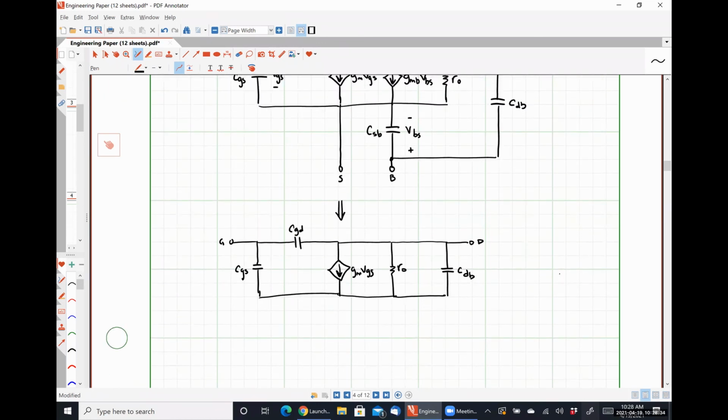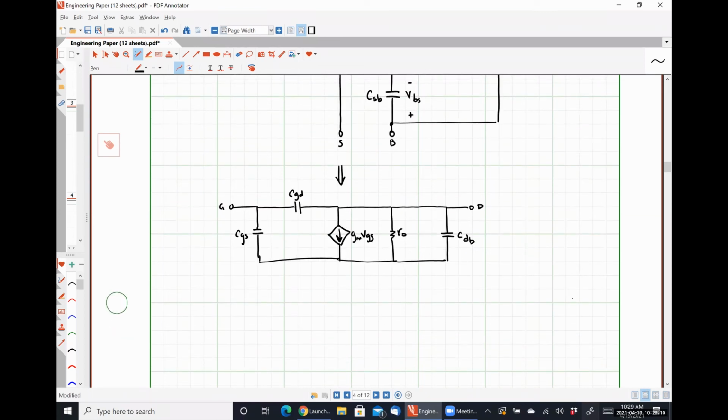And so here's something where legitimately I'm a smidge confused, okay? In the textbook that you guys are using, it explicitly draws a source to body capacitance even when the body effect is ignored. But that capacitance is shorted out, so I don't know why it's there. And in literally every single example problem, they say it doesn't matter because it's shorted out. So I'm going to draw it because the textbook has it in there, knowing full well it's going to be neglected literally every time we see it, okay? So just want to be real clear about this. So this is our source.